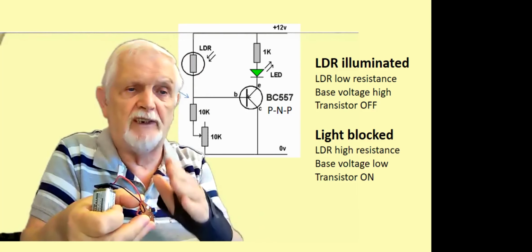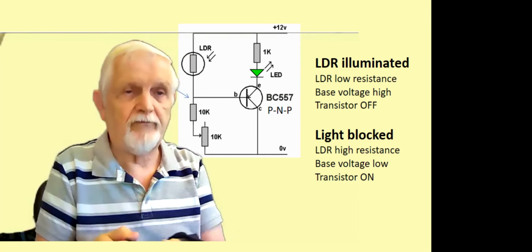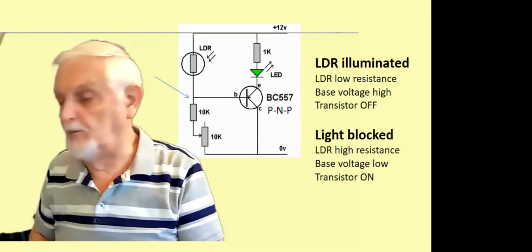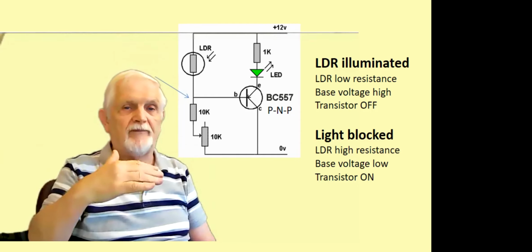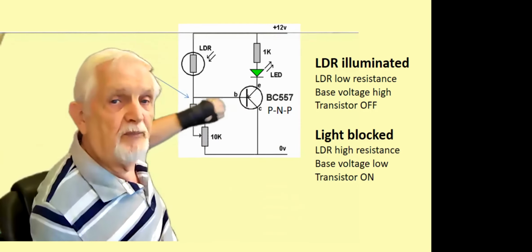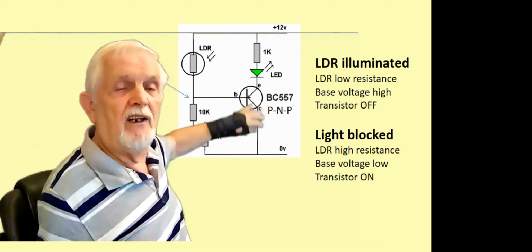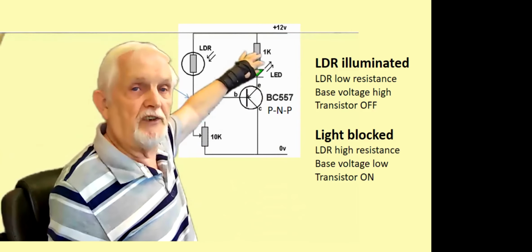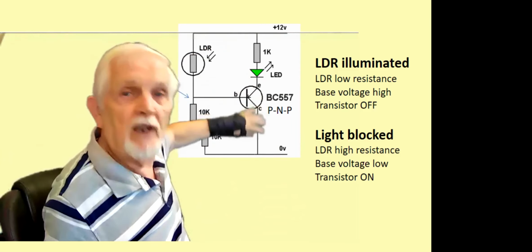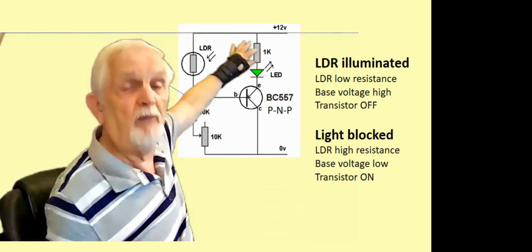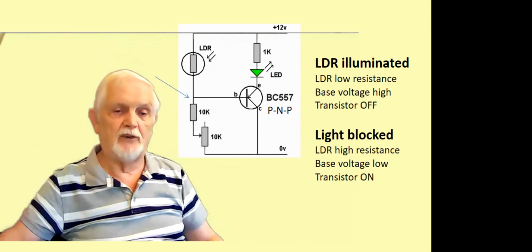There's intermediate, I don't know if you can actually see it, intermediate amounts of illumination coming out, because we're in that zone where it's a current amplifier. So the amount of current that's flowing through this piece here is increasing the current flowing through there up until you get to the point of saturation. If I fully cover that, then we saturate this diode, the full current that it can pass will be passed. So we use that principle there for the LDR train detector.